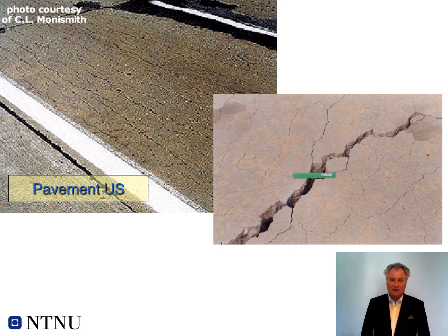Of course, that is not a very good situation. And actually in Norway, there was a need, and one airport started to get cracked like that. They needed to remove the whole concrete pavement and replace it with a new pavement with a non-reactive composition of the concrete.